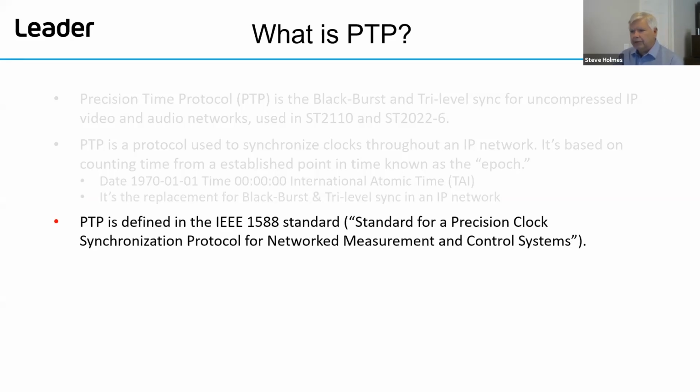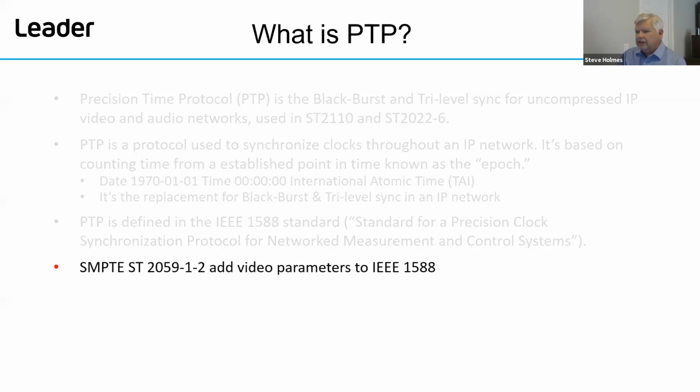PTP has actually been around for quite some time. It is standardized in IEEE 1588. It's the standard for precision clock synchronization protocol in network measurement controlled systems. The thing that SMPTE has done in 2059-1 and -2 is added the video parameters that did not exist in the original IEEE 1588.